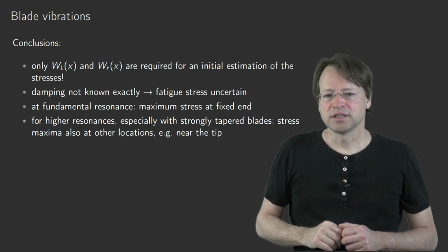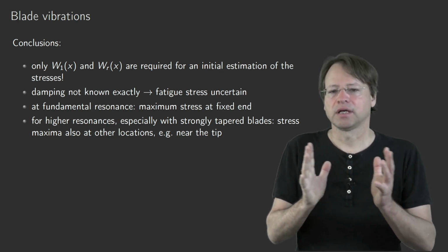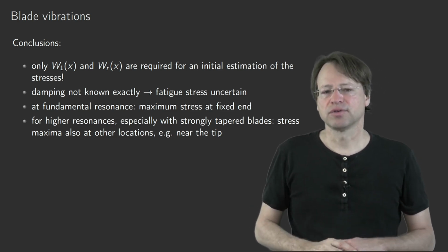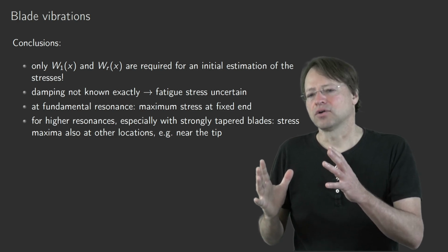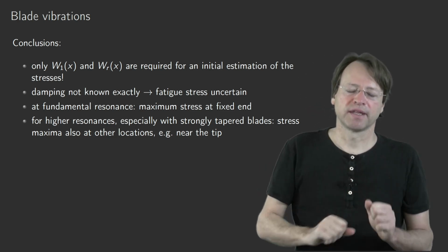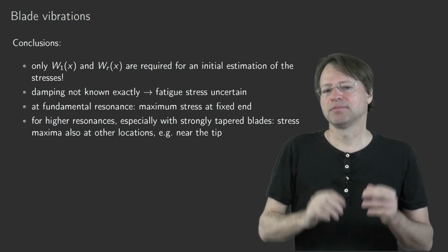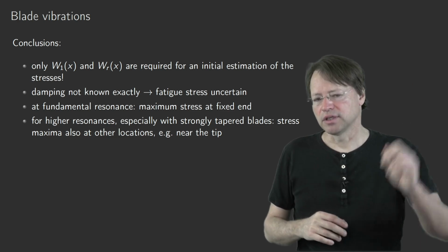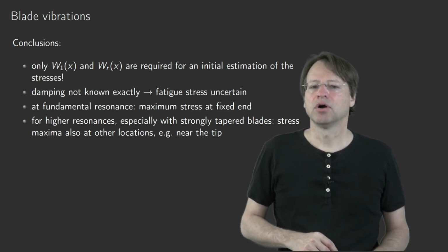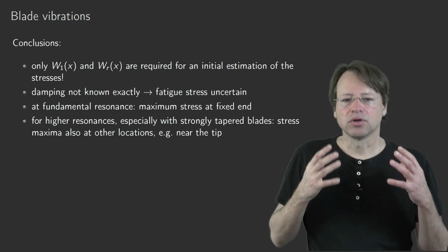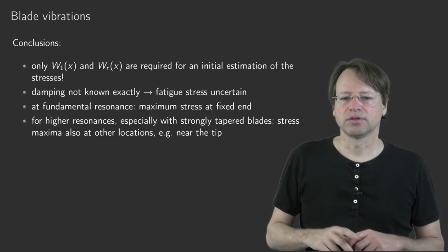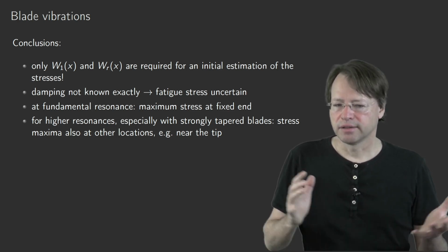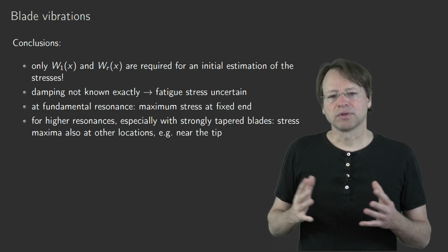And what you would then see if you introduce slight disturbances of the geometry, of the symmetry of that structure, then you will find a concentration of some modes and mode shapes, so therefore also the amplitudes, on certain blades, and especially on the tips, also on the tip forces on these blades. And this leads also to safety factors that have to be taken into account when designing these blades. And well, these safety factors, one tries to reduce them.